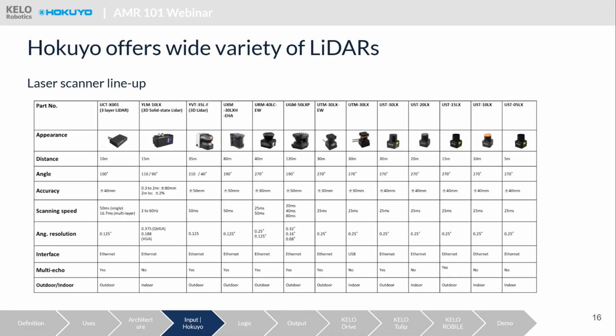Yes. So this table includes a subset of scanners in our lineup and overall specifications like distance, accuracy, and response time. These are basically all the models that provide raw measurement data. However, some scanners are considered hybrid models, such as URM40 and USD30LC, where it is possible to set obstacle detection zones in the scanner, in addition to raw measurement data output.